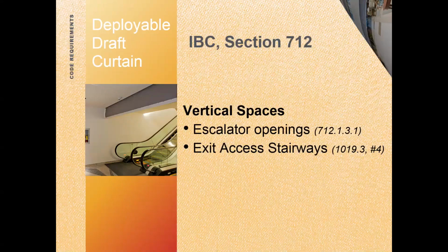Deployable draft curtains, we touched on these a few minutes ago. So this is the last of the 4 instances in the applications that we're going to see this fabric product being used. So once again, vertical spaces and escalator openings and exit access stairs. The only requirement is that it's made of non-combustible materials.